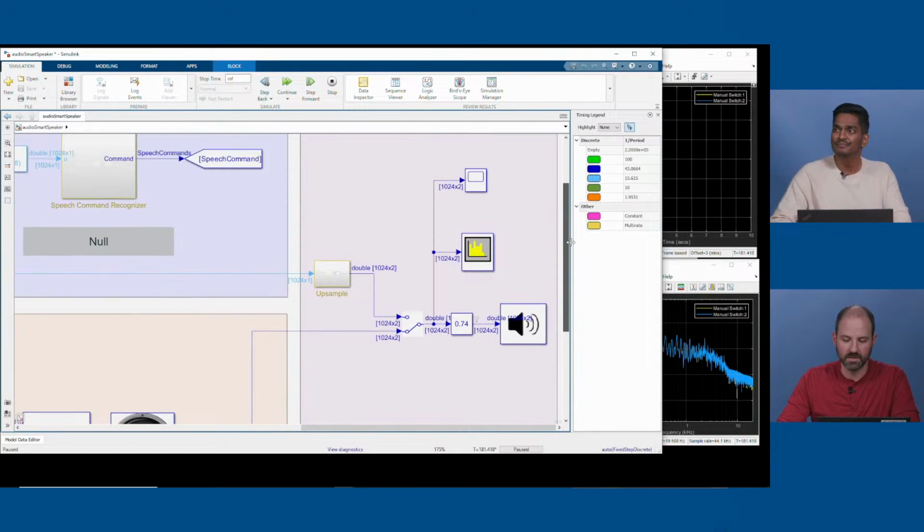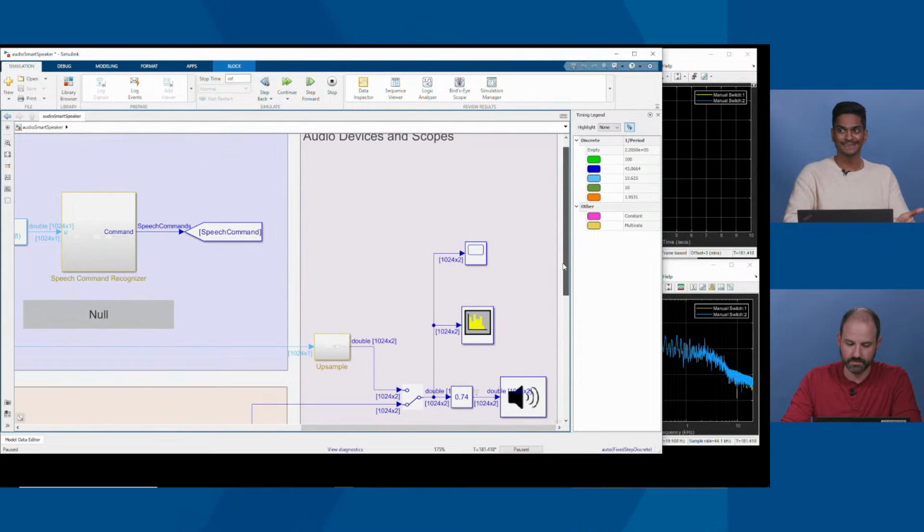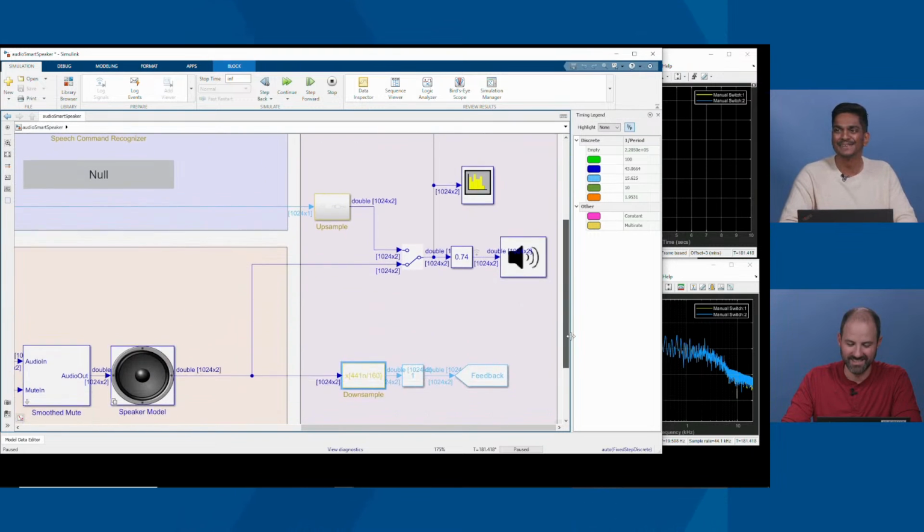Again, this is one of those things where in comparison to hand coding, this is so much easier. When you start mixing sample rates in hand code, you have to do a lot of manual scheduling to keep track of, okay, now this frame arrives after this many ticks, and this frame goes out after that many ticks, and it can get really messy. The timing engine in Simulink is really helpful for that. And you did say frames, so we should talk about those numbers there.